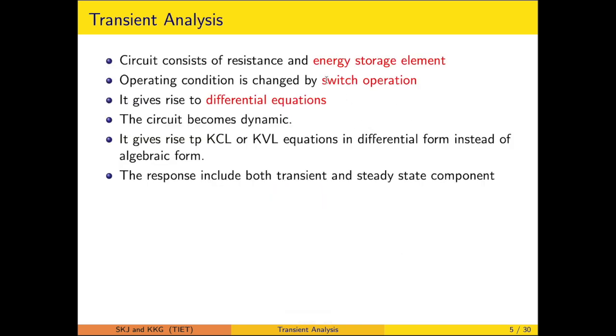The transient situation arises when the circuit consists of energy storage elements, that is either an inductor or a capacitor, or a combination of both. This further arises because there is a switch operation. The important point here is that instead of algebraic equations, it gives rise to differential equations of KCL and KVL. Because of this time dependency term, the circuit becomes dynamic, and the word dynamic itself carries the meaning that it has a time dependency. This includes both the transient and the steady state components in the response.